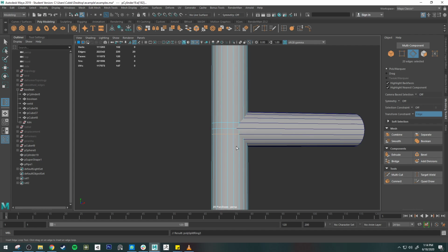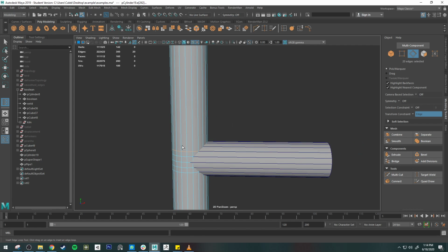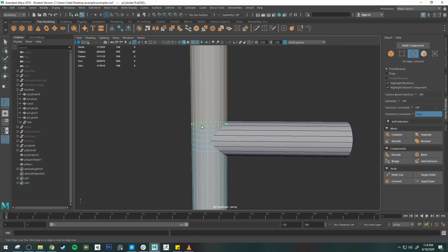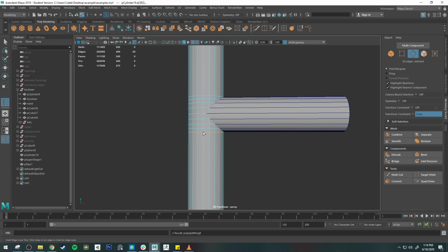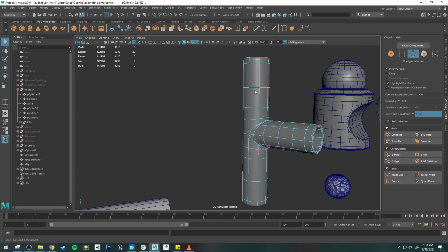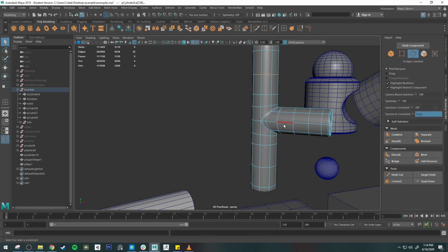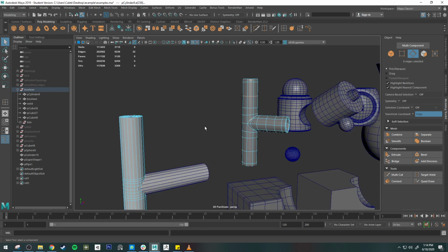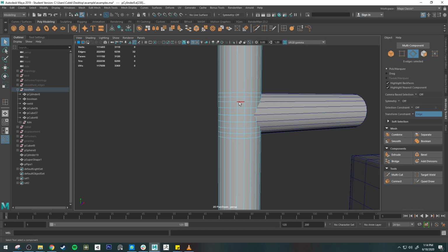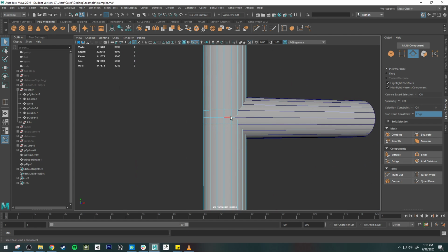All right. We can probably get rid of some of these guys once we're done with it, just to reduce the number of poles. I'm just going to put them there in preparation. A lot of this is easier to do while you have your object, before you actually weld these objects, right? And I probably don't even need all these edges, because as you notice on this one, this is 8, right? I didn't really need to do that for this one. I just had one going across that way just to keep the topology okay in that area. So I probably don't even need all these edges going that way. So let's go ahead and get rid of these. I'll do Control Delete to get rid of those vertices and the edges.